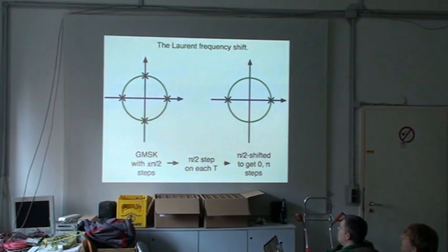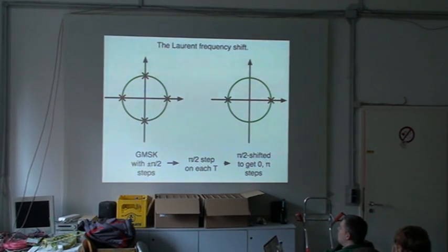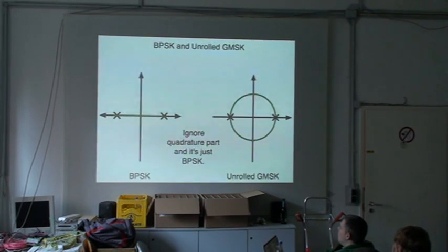And that 90 degree out of phase complex component is what's causing the signal to transition off of the real axis during transition periods. But the other part of this is, if you remember back when we talked about ISI from the channel filter, nearly all the intersymbol interference that's inherent to GMSK is happening along the imaginary axis.